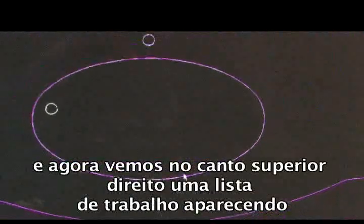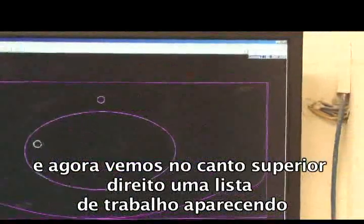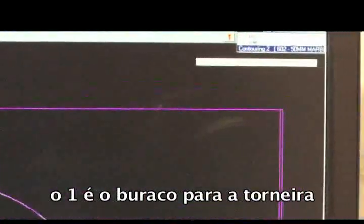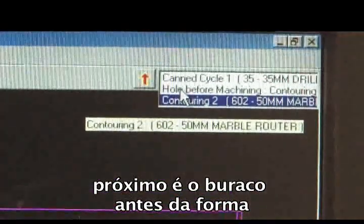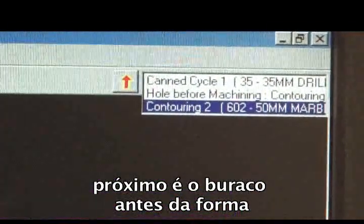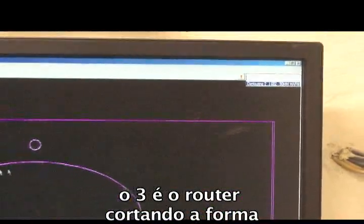We select OK for the drill, and now we can see in the top right hand corner a machining list starting to appear. The first one is the drill for its tap hole. Next is the drill before our router cuts the shape, and the third one is our router cutting the shape.